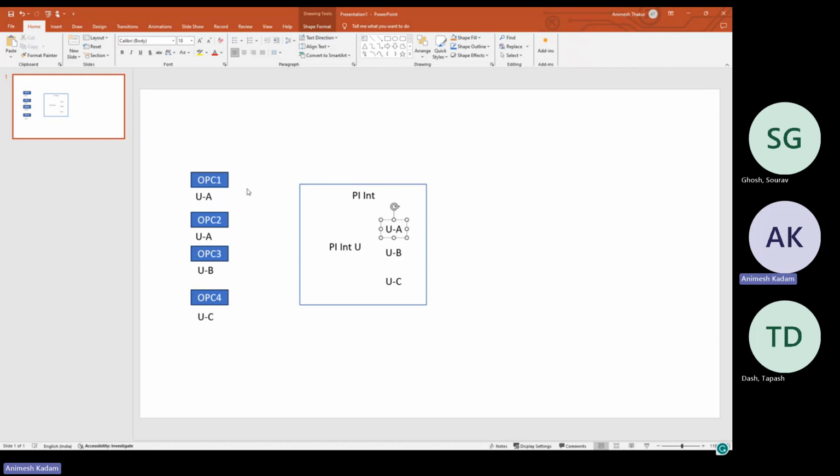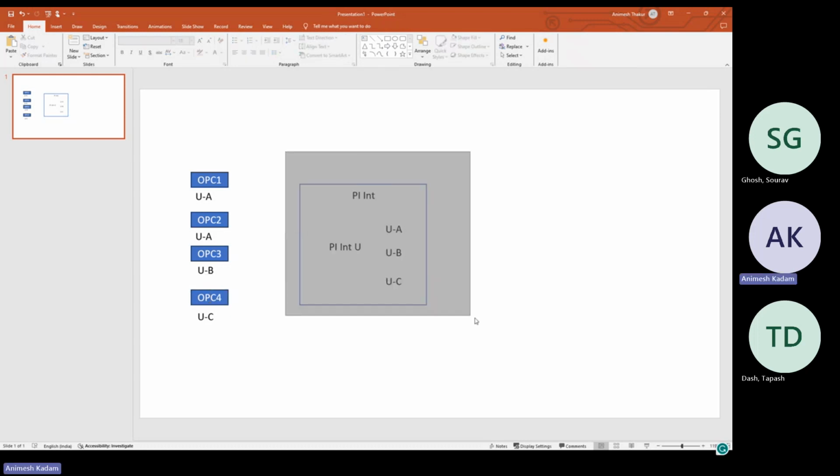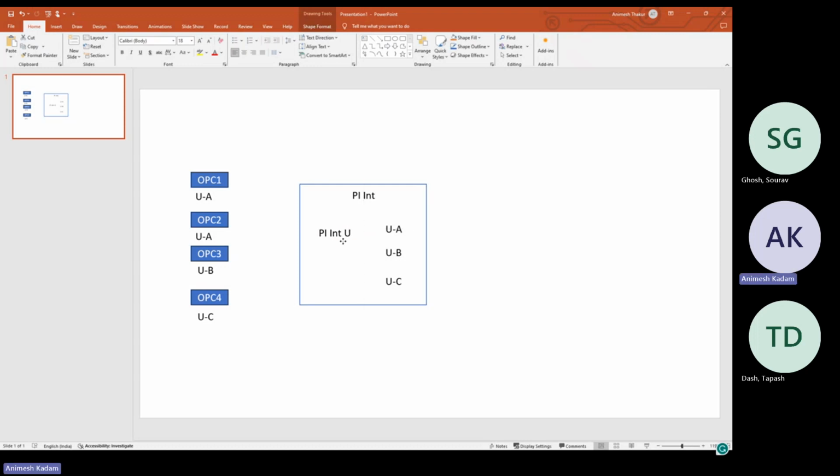But now you will be doing DCOM here also, here also, here also, and here also, on all these OPCs. You will be doing DCOM on this system also. The difference is that most of the DCOM settings will remain the same. At the time you add a new OPC server, you only need to add that particular user in the DCOM setting for that OPC. Understand? Or should I repeat?